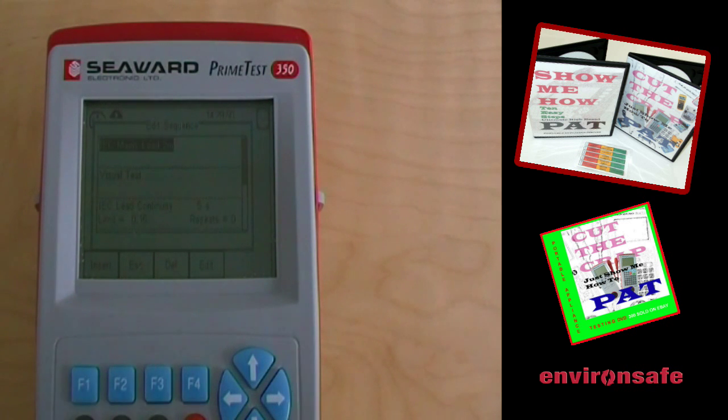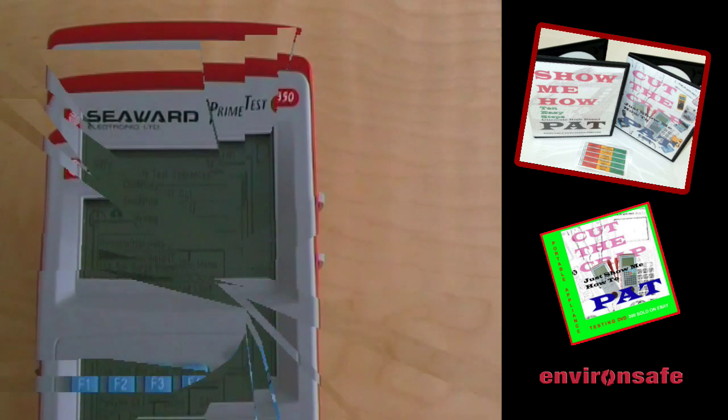We're going to edit, and they are visual tests, IEC lead continuity at 5 seconds, insulation at 500 volts, and the polarity, the IEC lead wiring check. And that's the end of that particular sequence, so we will escape from that. Escape again.